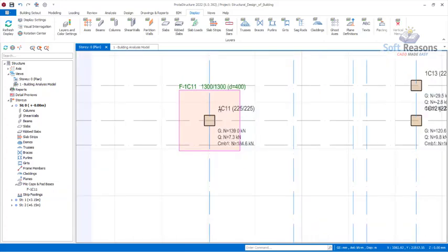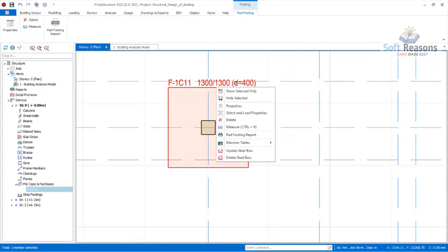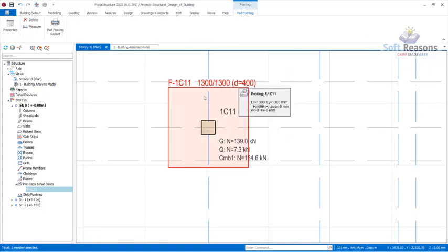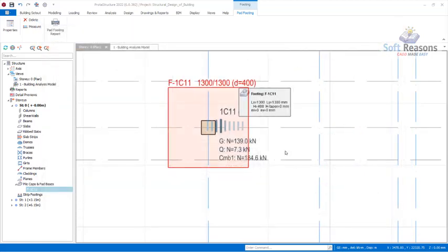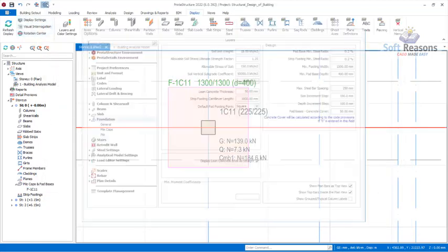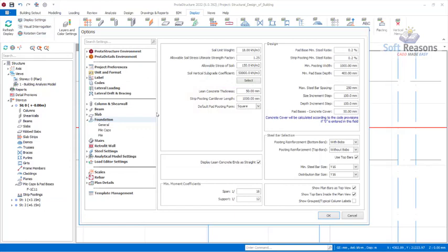Okay, so if you want to check this manually, you can check it using the soil bearing capacity. We change it over there in the settings, so let's go and confirm that right away. You can come to the setting center, then come to these provisions, foundations. The soil bearing capacity is 150 right there. So this is the minimum pad base.